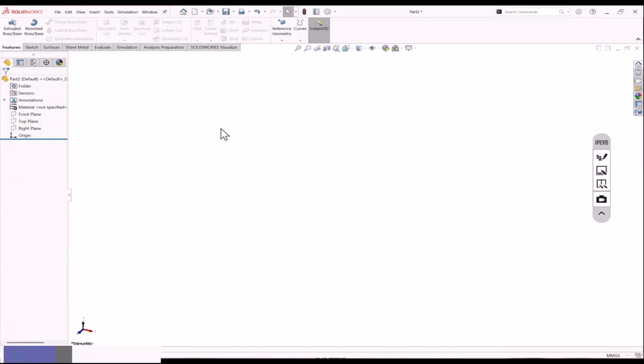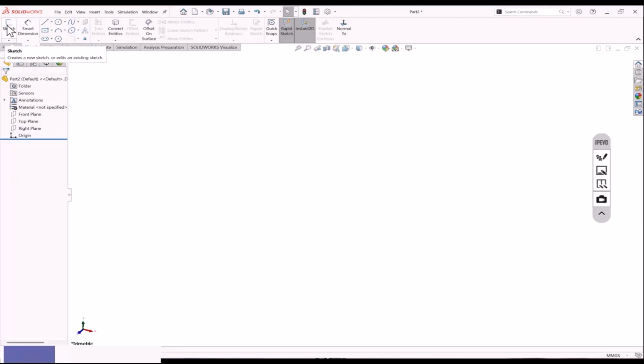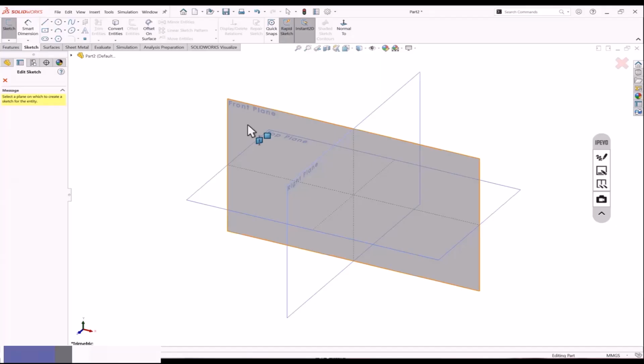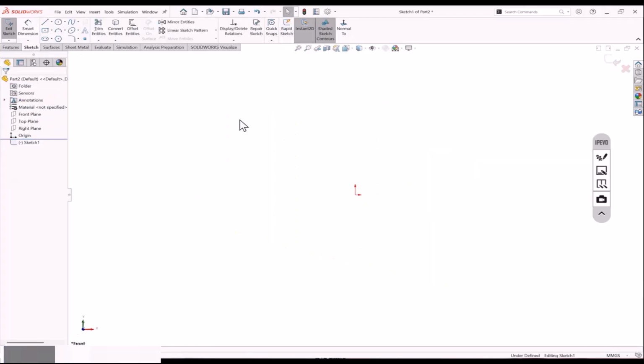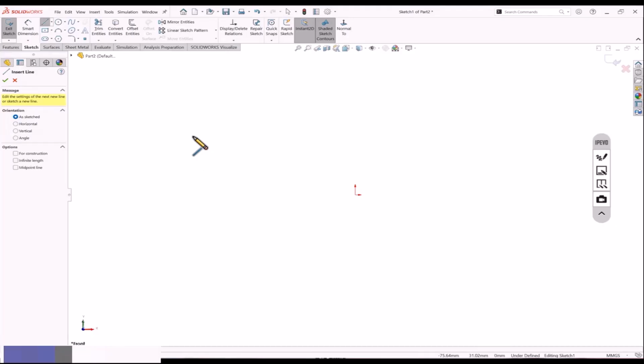Okay. So let's start now. How to do sketching normally. First we take the sketch tab, then go to the sketch icon, and then we have to select the plane. Now we can use these options. We'll start with all these options now. The first is the line command. Some command shortcuts are there, not all. For line, they have given the shortcut L. You can press L and activate that.